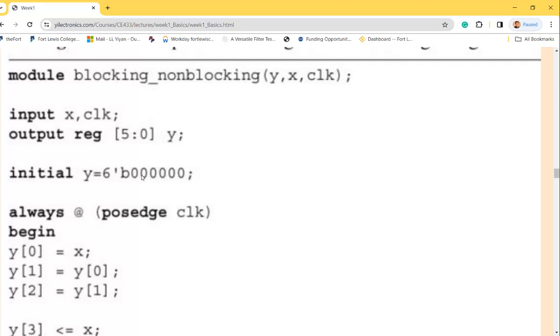You don't have to really know how to design that little register circuit, because that's being taught in digital electronics. It's CE330A. So now I just need to know it's a register which can register something into it. Okay, the register type with 6 bits in there. The reason I want to define that one as a register type is because I want to assign an initial value to it at the very beginning, which is the initial 6-bit prime.